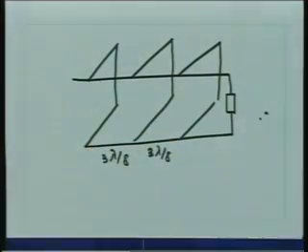So the final solution in impedance matching is the 3 stub technique, by which all possible impedances can be matched without moving the location of the stubs on the transmission line. That completes the discussion of the impedance matching of an unknown impedance to the characteristic impedance of the transmission line.